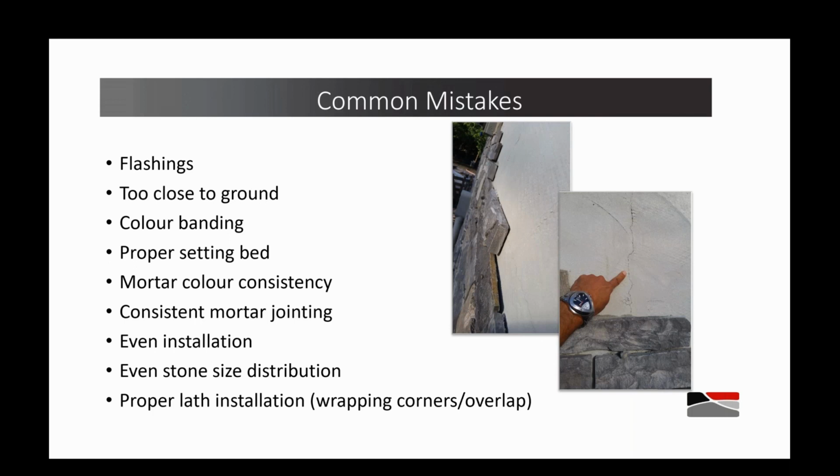There's zero evidence to suggest that that's even likely, let alone a fact. In fact, what it does do is create a void behind the stone where moisture can accumulate, and then you can get into a freeze-thaw situation, and obviously you can see that stone pop off the wall because of that. We often see mortar color consistency issues, inconsistent mortar jointing, and uneven installation and stone distribution.